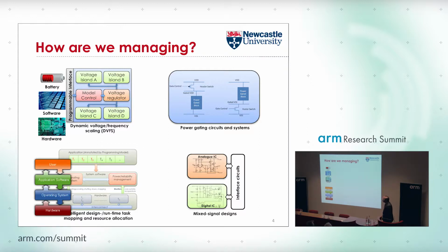Now, the job of maintaining the trend-setting curve of energy efficiency with this limited battery technology has been done by low-power design. And the low-power design techniques, if I name all of them, obviously there will be so many of them. I just happen to mention only 4 of them. These are the major innovations in the space of low-power design. The first and foremost one is dynamic voltage and frequency scaling. This, I believe, is the most significant innovation since low-power design has come into place. Then power gating circuits and systems, which is where ARM has a lot of contribution over the years, especially deeply embedded power gating.